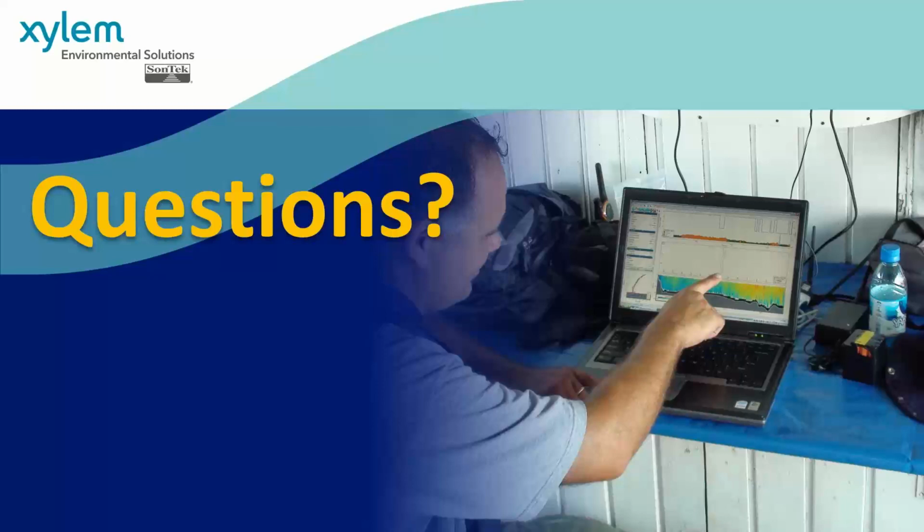But then we also have the option with the M9, we also have a Hydro Surveyor M9, which can be used with HYPACK surveying software. So you can run the Hydro Surveyor M9, the same hardware, with HYPACK and do an actual bathymetric survey, and at the same time you're collecting water velocity data as well. So that's a good question. And if you're after strictly bathymetric data with flow data being secondary, the Hydro Surveyor would be the way to go.